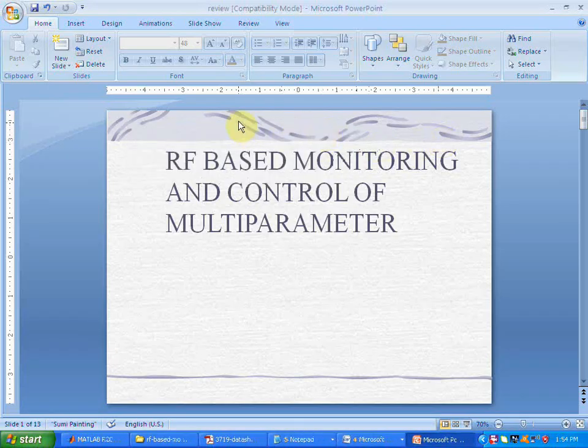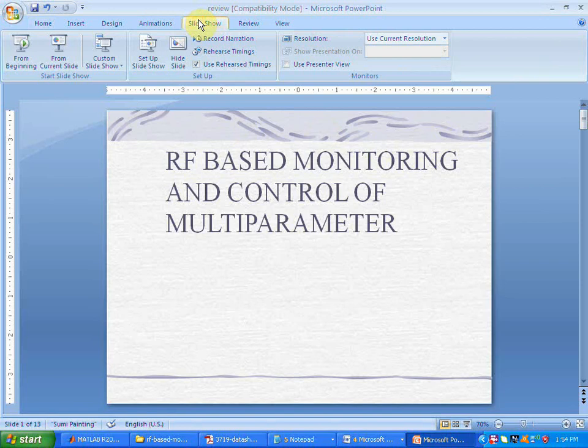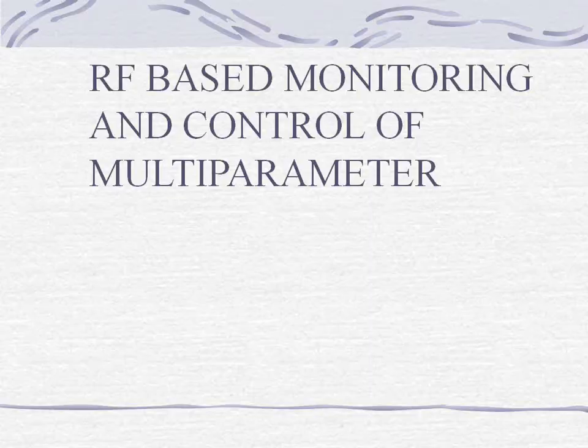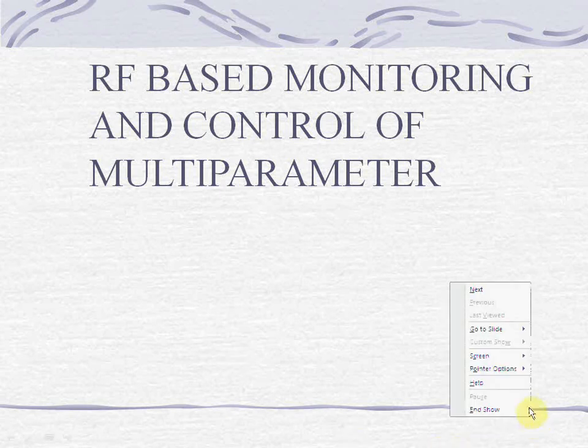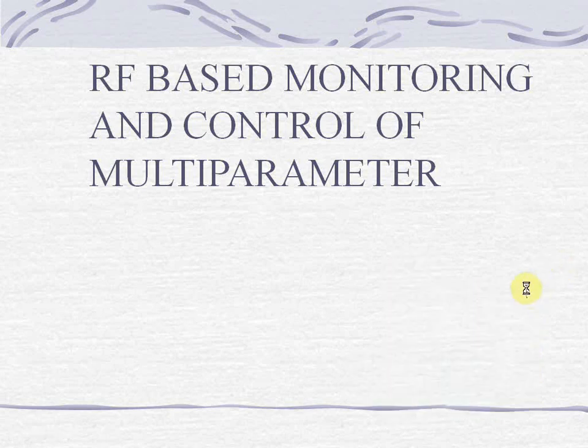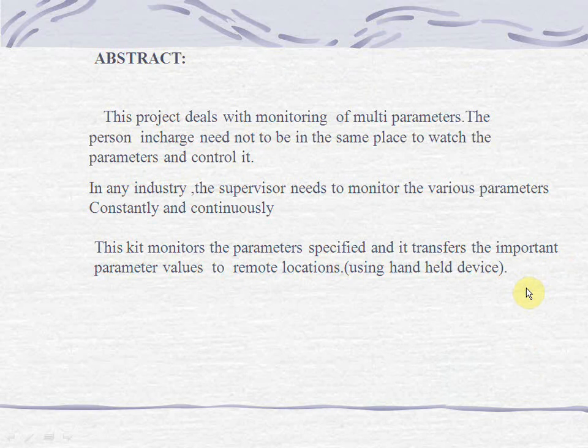A separate setup is used for monitoring the voltage, current and temperature, and for all these things the processing unit is the microcontroller. The internal ADC of the microcontroller is provided with a 2.5 volt reference, and based upon this reference voltage, the analog signals corresponding to voltage or current or temperature are read by the microcontroller.